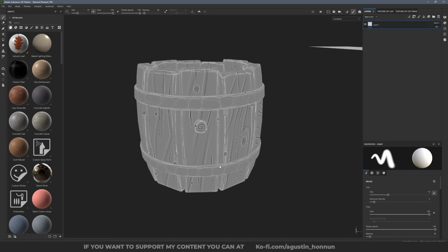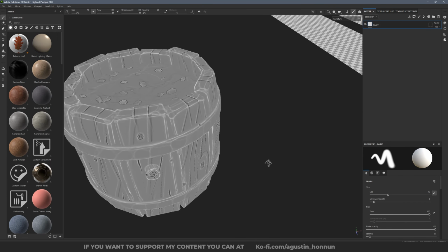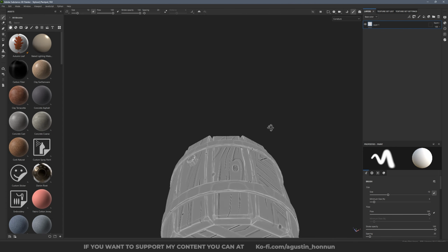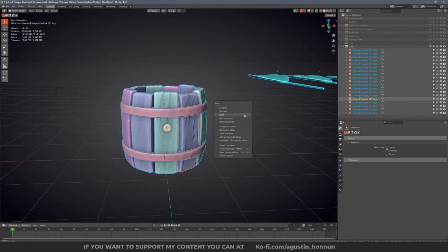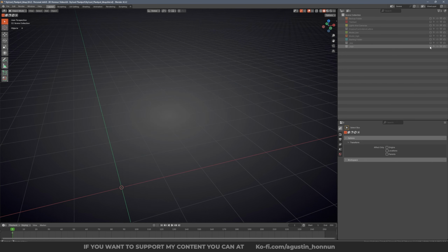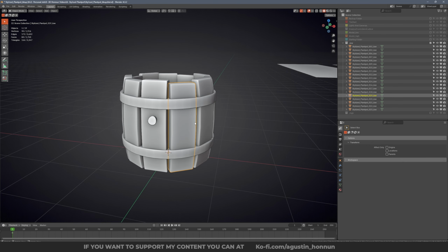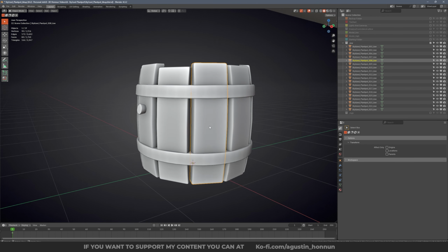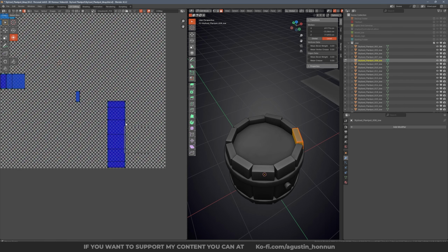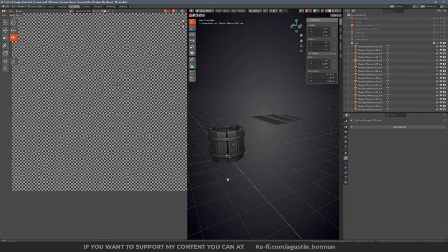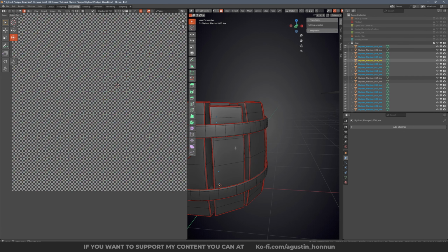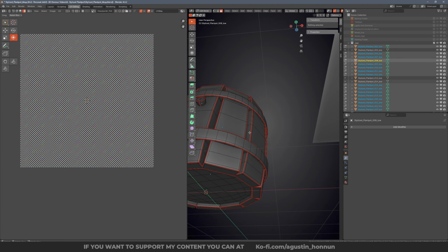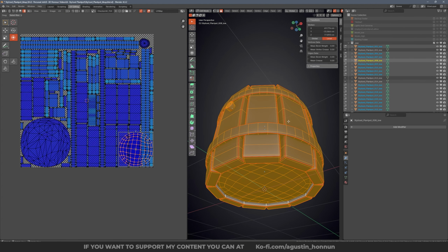Okay, identify the meshes where you have problems. It seems to be only this face and the bottom face. So go back to Blender. First, make sure to apply scales and rotation to the high poly objects, so you don't have problems later in the bake. Here select this object, and let me check if the problem is here. Okay, select all the barrel, and yeah, I see the problem here. I moved this bottom part to show you something, and I forgot to fix it.